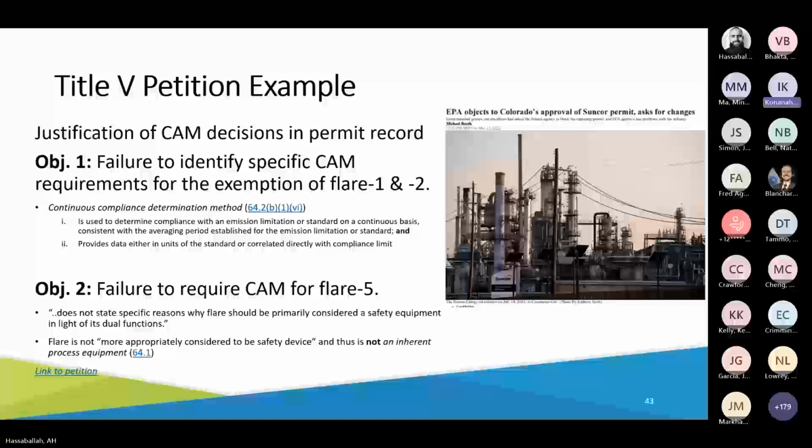This question is about the flares. The flares, yes, they should have a pilot lamp to light the combustible fumes coming out. But there is another method some people are using, although they are not major sources, that this gas is almost negligible, and they're using once in 5 seconds spark to burn the combustible gases if they are coming out.